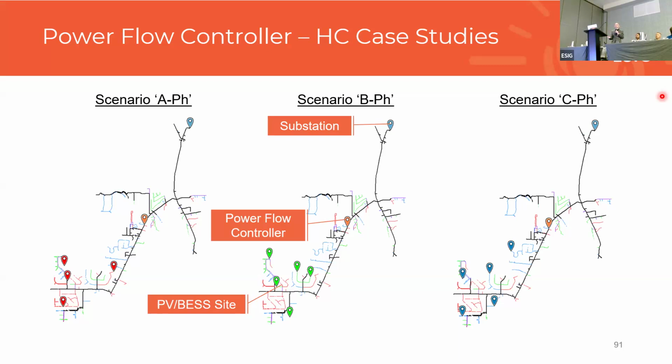And also because it dynamically balances, if you had a high penetration of residential that is fluctuating with, let's say, just clouds or whatever the case might be, it is going to dynamically adjust in the seconds period, similar to what the PV is doing, and it will help to smooth out that, and it'll transfer that power phase to phase to make the system look more balanced throughout those transitions.